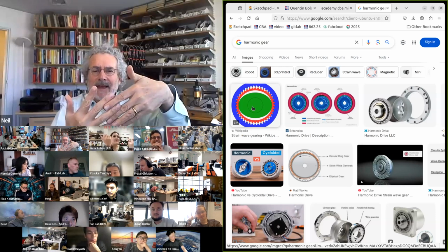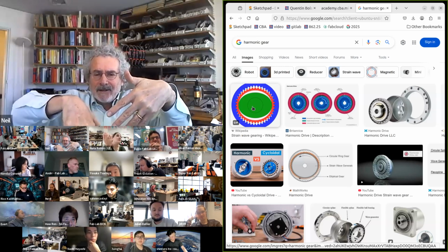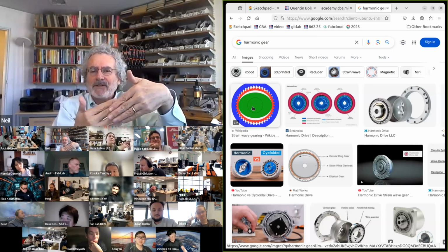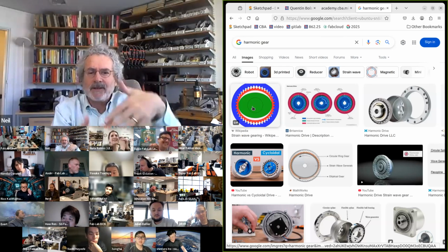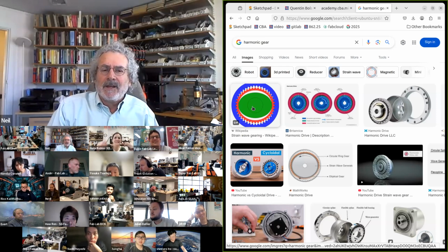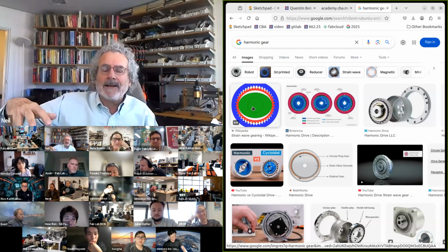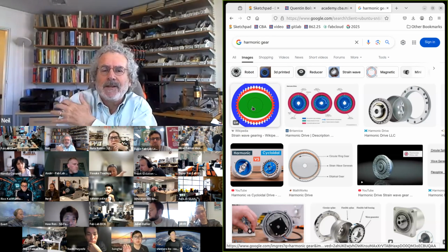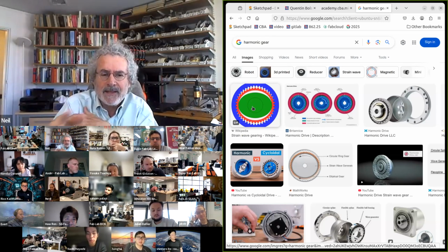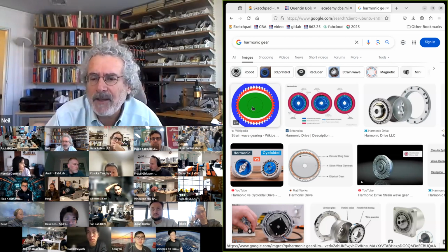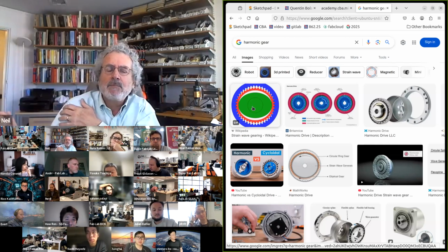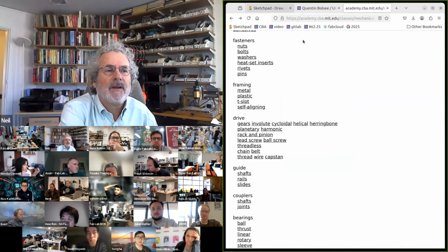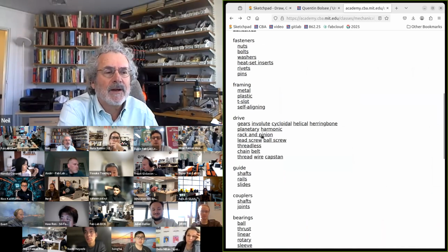So as the deformable inner moves with the elliptical drive, when it comes all the way around again, because they have a different number of tooth, the alignment can change by one tooth. So when you look at a robot, like a robot arm or a robot dog, this is the most common thing used in the shoulder of the robot. It lets a motor spin at a higher RPM where it's efficient, but smoothly and slowly move the joint. Okay, so that's a harmonic drive.